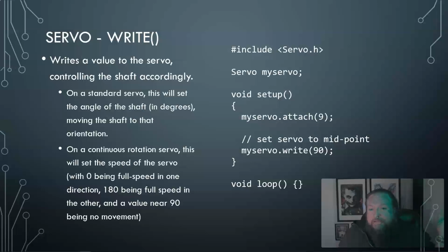I've bought stuff for the course before that had all the same markings, but either due to me not understanding something or the manufacturer, they were marked as standard hobby servos, but instead they were actually continuous. So the same code that I used started working differently. So again, if it spins all the way around, you've got a continuous servo. You don't have the normal hobby servo.